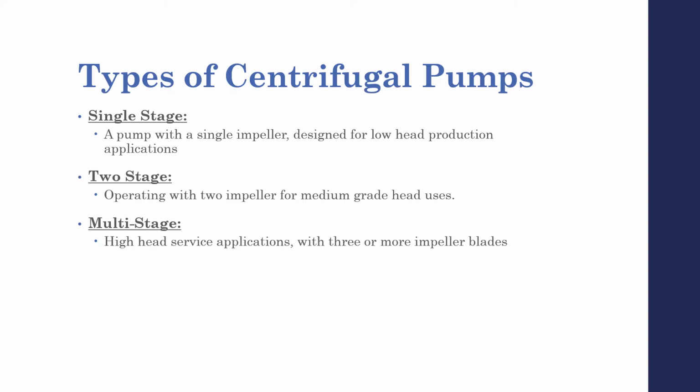And then you have the two stage, which operates with two impellers for medium grade head use. They ensure a more reliable, high efficiency process and lower operating costs. And then you have the multi-stage centrifugal pump, for high head service applications with 3 or more impellers.